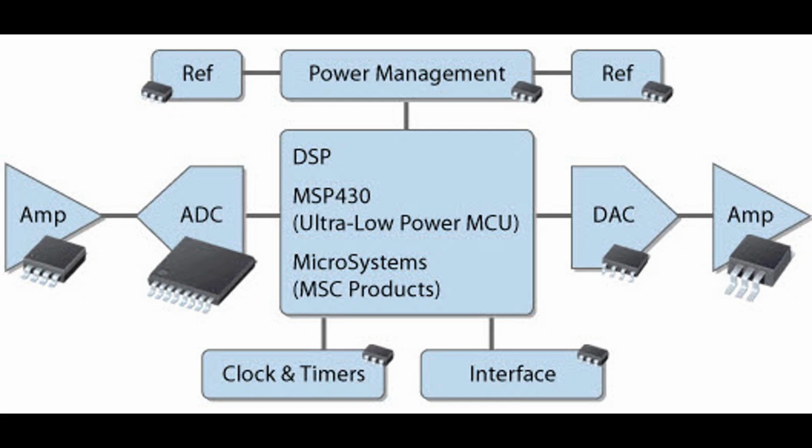Truth tables. Truth tables are used to define the behavior of logical operations. A truth table shows all possible combinations of input values and their corresponding output values for a specific operation. For example, the truth table for the AND operation is as follows: A, B, A AND B. 0, 0, 0. 0, 1, 0. 1, 0, 0. 1, 1, 1.